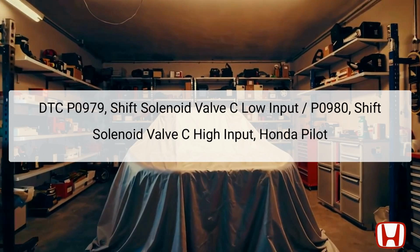This presentation will focus on diagnosing the DTC codes P0979 and P0980 associated with the Honda Pilot models from 2016 to 2022. DTC P0979 indicates a shift solenoid valve C low input issue, while DTC P0980 refers to a shift solenoid valve C high input. Both codes point to a problem in the electrical circuit rather than a mechanical failure within the transmission system itself.